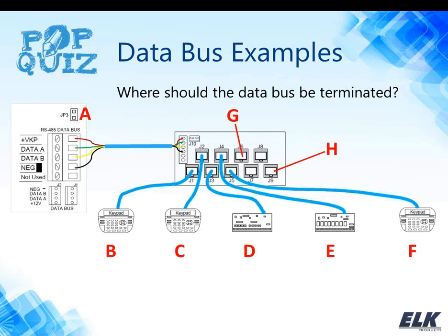All right, I've got a lot of correct answers on this one, which just goes to show how the hubs simplify things for you. So Jonathan, where are we terminating on this one? Terminating on A and G. A and G, and why is that? Because you only got 1 home run, and you have to put that little RJ45 connection in the last open slot on the M1DBH, which would be slot J6, it looks like, which was G. That's right.